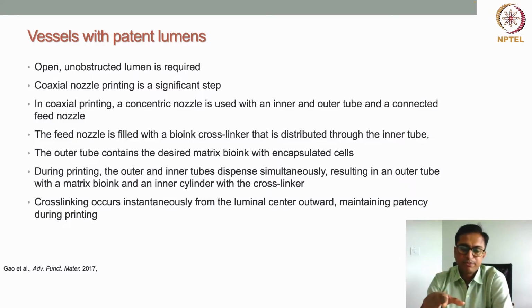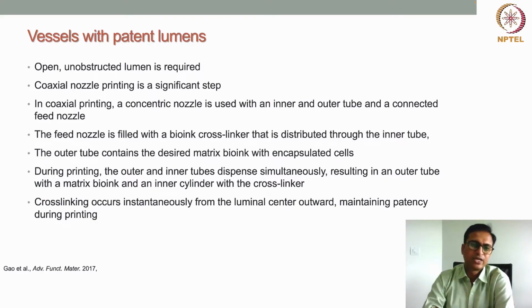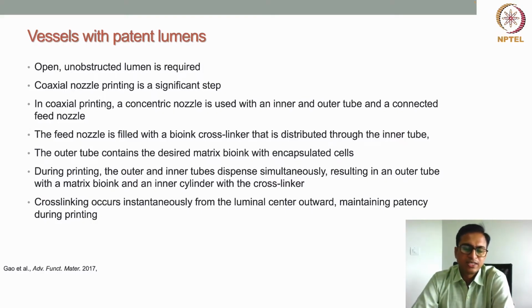This kind of concentric nozzle has a very special application where two different materials are used. The biomaterial, or bioink, can be extruded through the inner core nozzle, and the crosslinker through the outer channel. In that case, the cross-linking of the bioink will happen as soon as the extrusion happens.